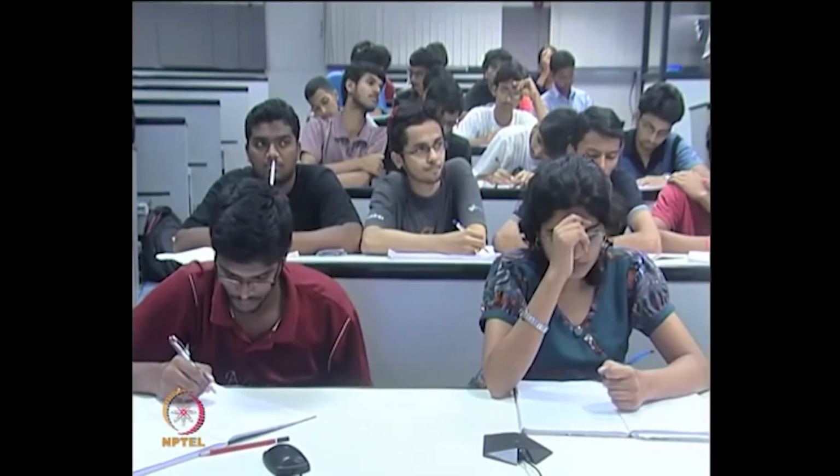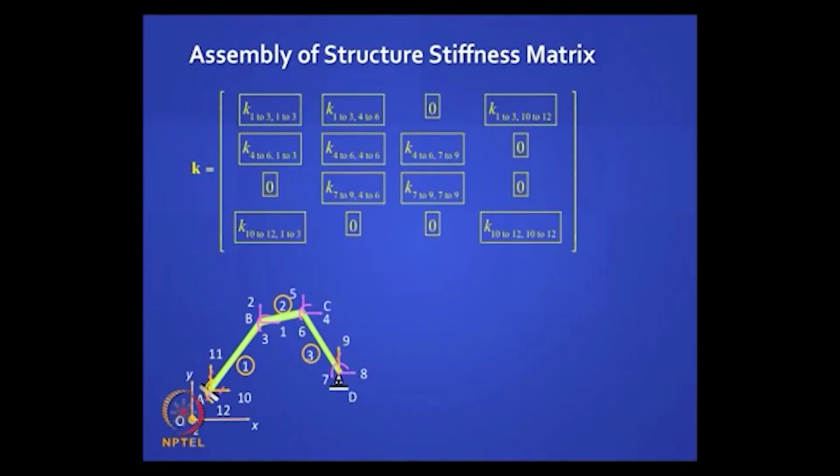So you have to just rearrange the rows and columns, you get 7, 8, 9. At the end of the day, this is what you need to do. This is your 12 by 12 matrix. From the first K1 you get this, so you have to appropriately put the boxes. And does this make sense to you? There will be some zeros, and this is my KAA, this is my KAR, this is my KRA, this is KRR.